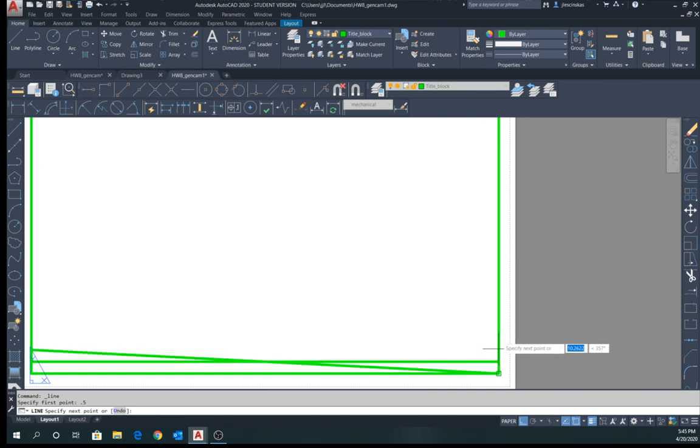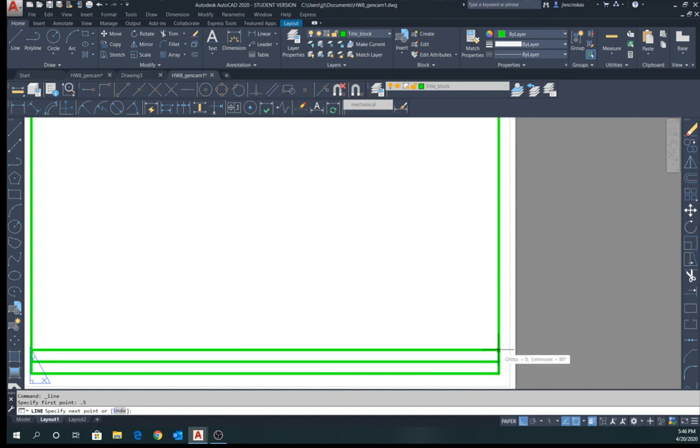And actually, we're not able to snap at that intersection this time. Why were we able to snap at that intersection previously? Because I came down to this corner and then brought the tracking up, and that allowed me to snap. But let's go back and see what we're missing. So why were we not able to snap at that reference point?